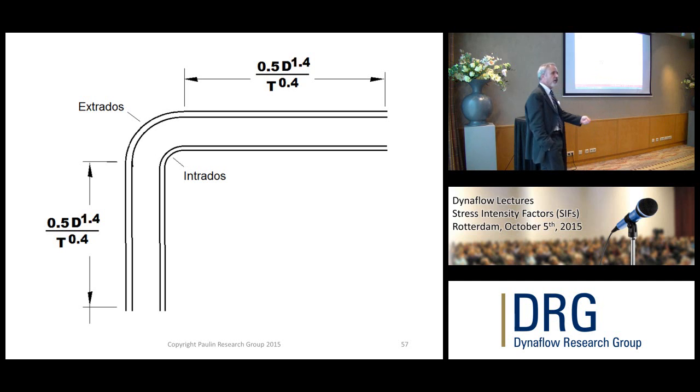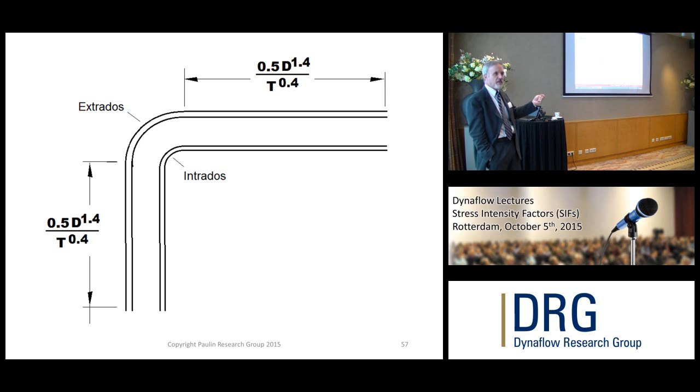Existing code equations for 160 or 180 degree return bends: the K factors, as we talked about, go down as you get to 45s. So if you've got a whole lot of 45s in a short system, what you're putting in is just completely off base. There's no reason for that. We can correct that. So FEA Tools corrects that automatically. So bends are one of the things that we've corrected.